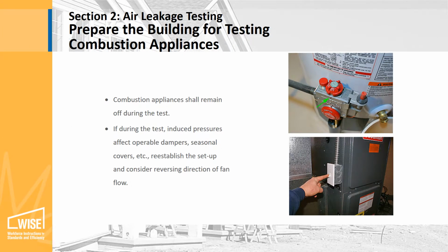Combustion appliances shall remain off during the test. If during the test, the induced pressures affect operable dampers, seasonal covers, etc., re-establish the setup and consider reversing the direction of the fan flow.